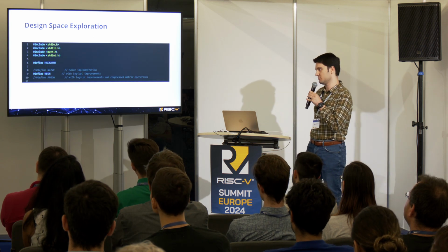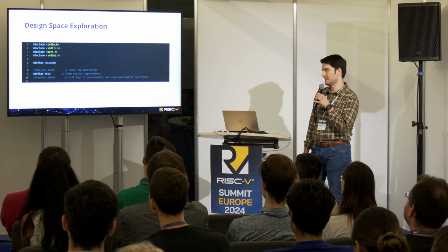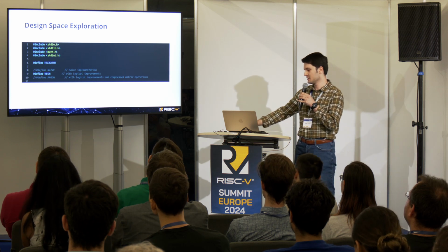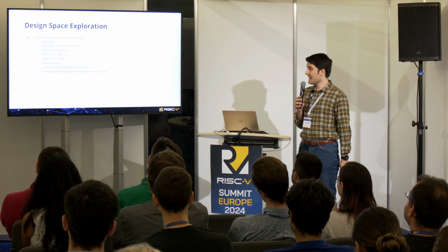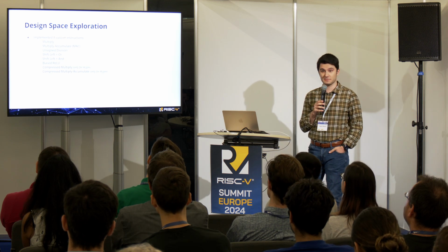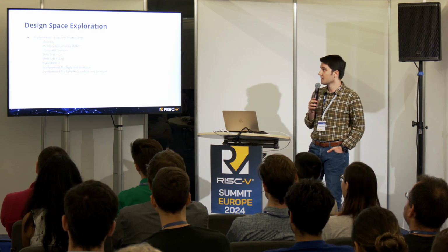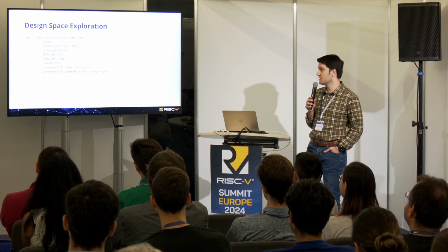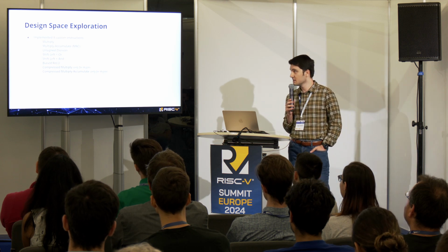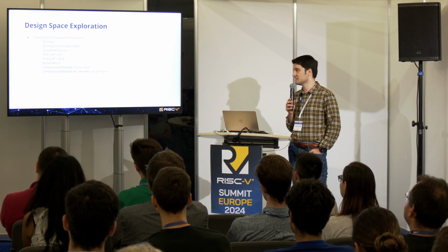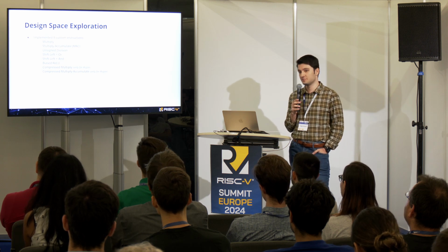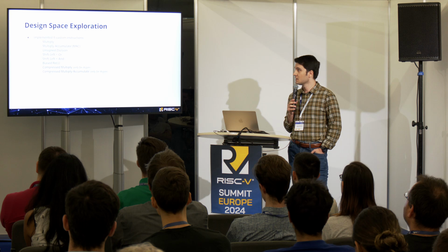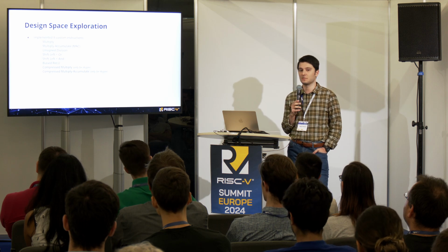And it's the idea I came up with very late, to be honest. Yeah, I implemented 8 custom instructions because we had place. Multiply accumulate, unsigned division, shift left and OR, shift left and AND, biased ReLU, and for compressed matrix operations, compressed multiply and compressed multiply accumulate.